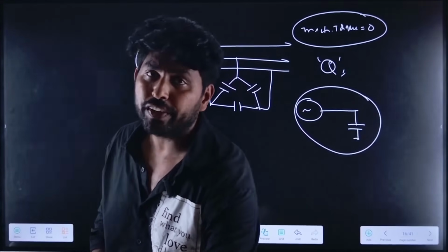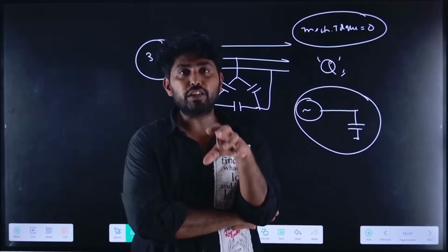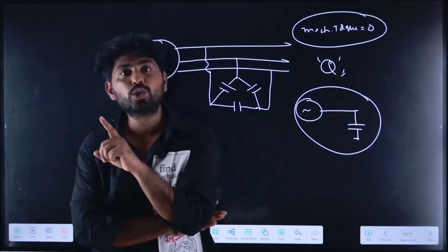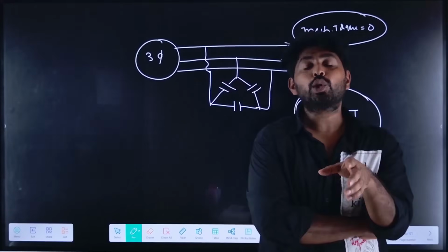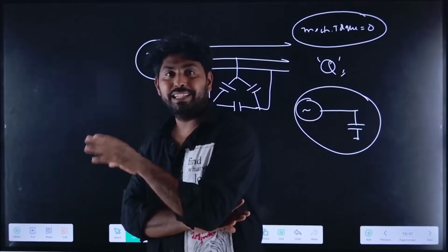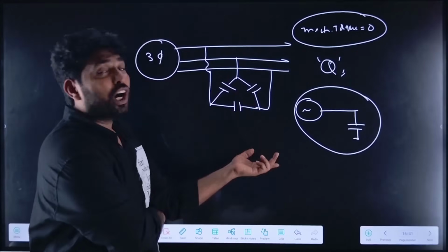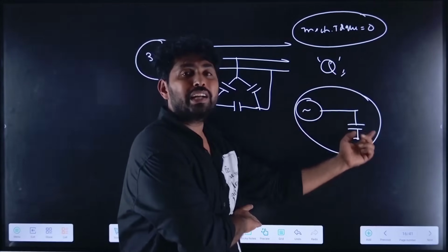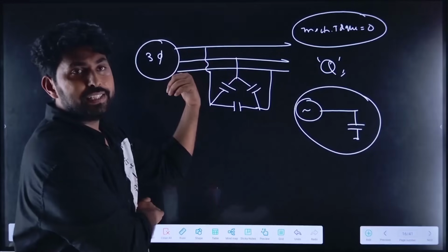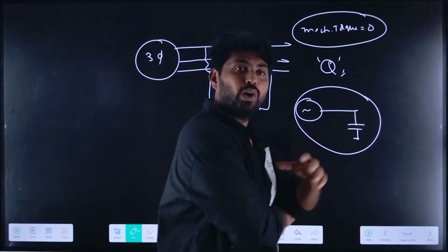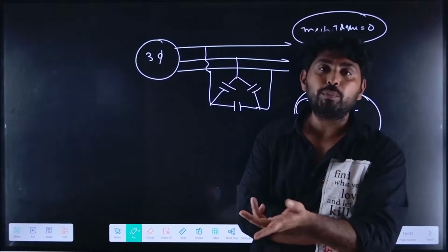But in case of a three-phase system, and this is an interview question, the reactive power is not an oscillating power. It is constant. The mechanical torque is also oscillating in case of single phase, but in case of three phase, the mechanical torque is constant. If you connect the capacitive load, there will be zero mechanical torque.